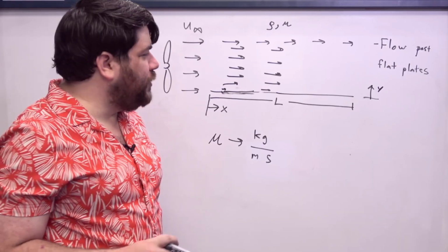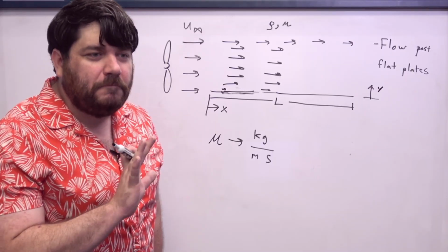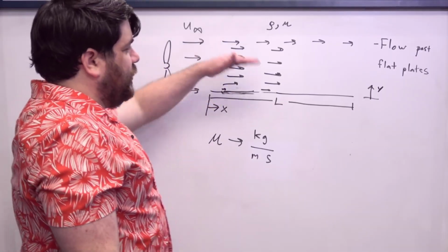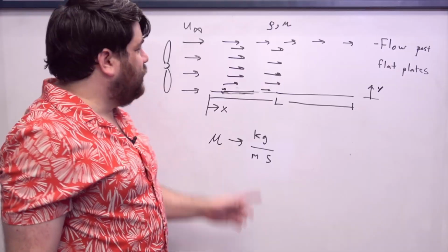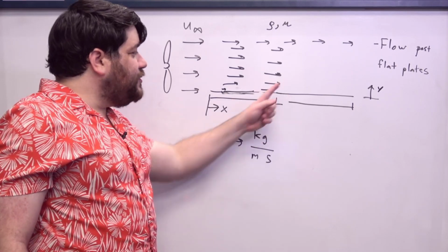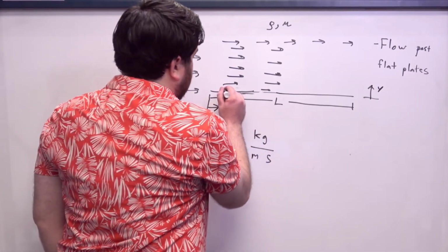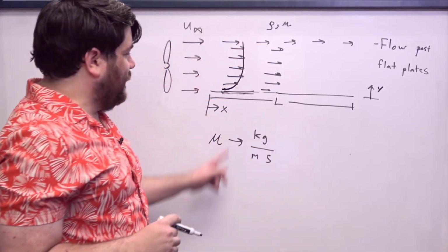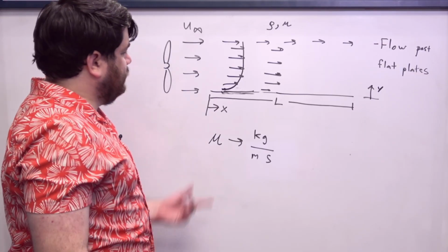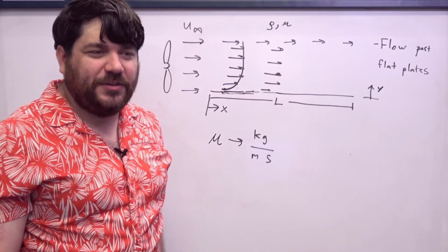In short, what is happening is the construction of a boundary layer, or a velocity boundary layer. And the reason for that is just the fact that we know there's a very large region past the plate where the flow has a speed that's very close to u infinity. And we know that there's a region over which this speed drops all the way down to zero. That happens very, very close to the surface of the plate. And so this is the flow pattern that we observe. Qualitatively, that's just what we see.